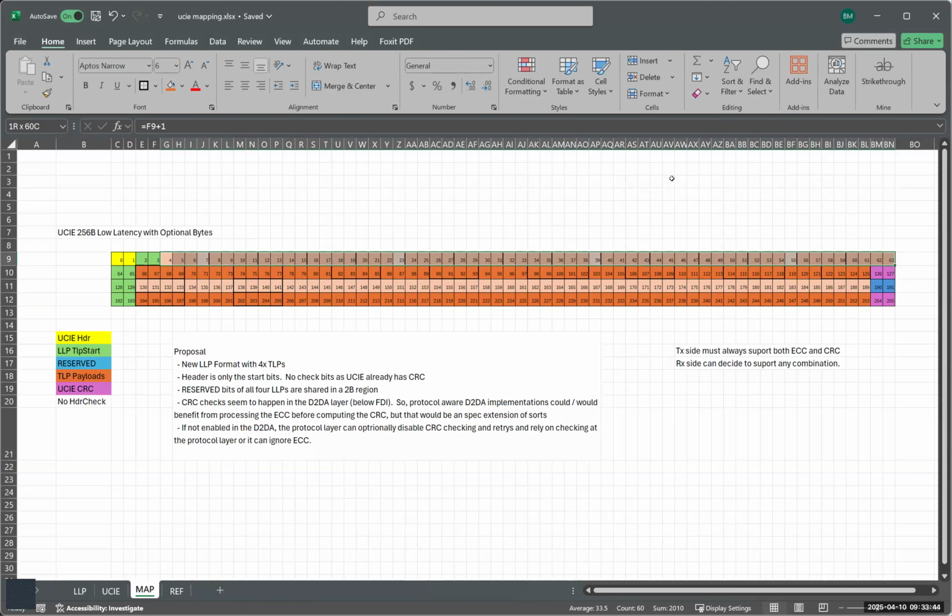All right, so you see the orange groupings, this is an LOP kind of as defined in the spec. This is the LOP payload, right? The header is normally 32 bits, but I've truncated it down to 16. But the actual payload of the LOP is unchanged from our current definition of an LOP. You just have 4 of them, right?